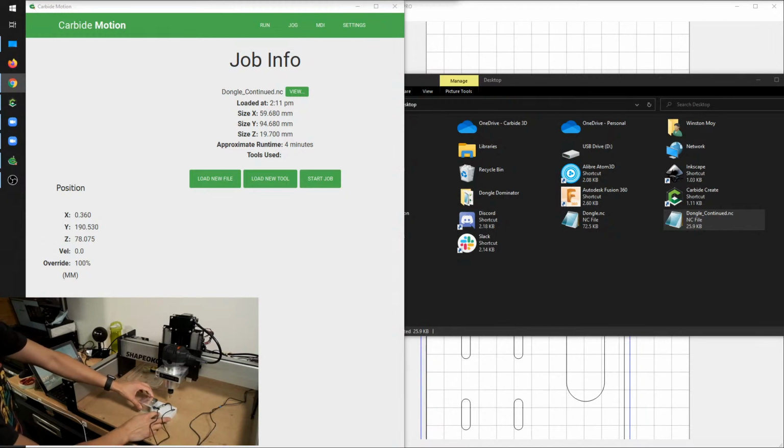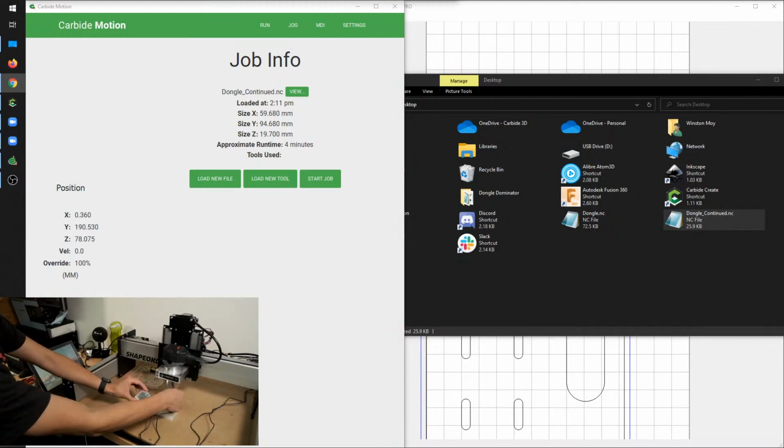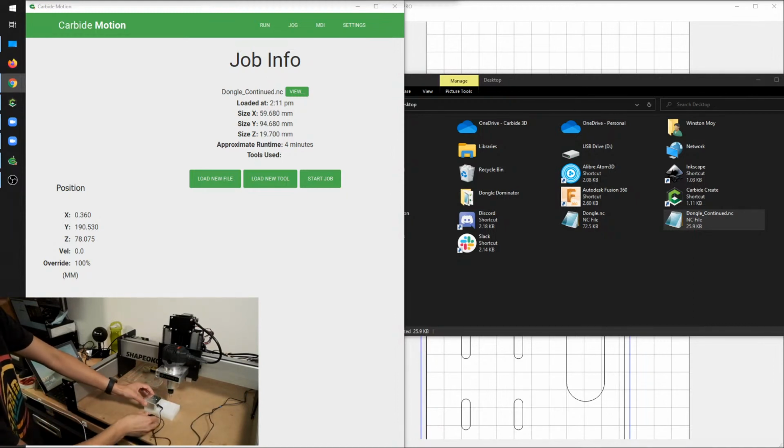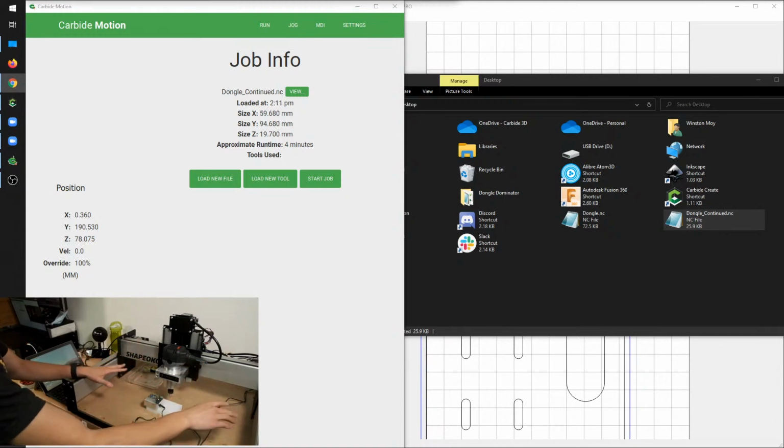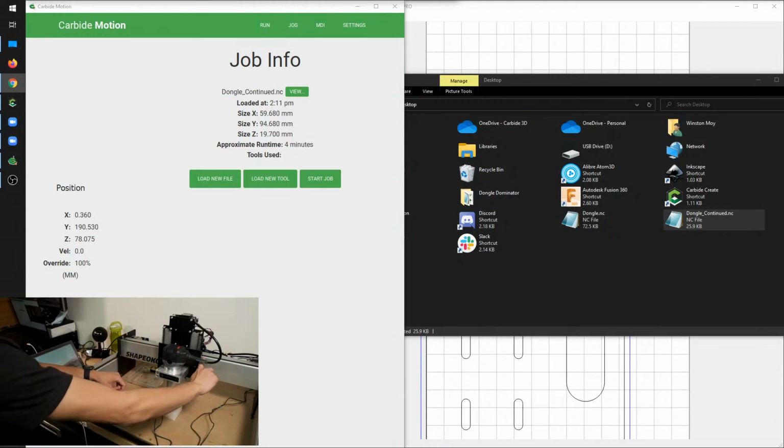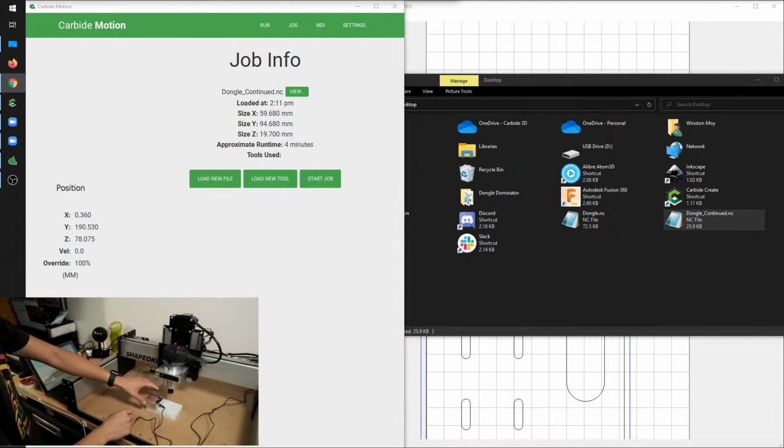So if you're just finding the Z, you throw it on this edge, so it's riding on top of everything. If you want to find the X and Y or X, Y, and Z, you throw it inside this ledge so that this corner is there, and it'll compensate once it touches off here and here for the diameter of the tool. And so that's how you find where your stock is positioned relative to everything else, more importantly, relative to where you homed off from. So that is what the BitZero does.